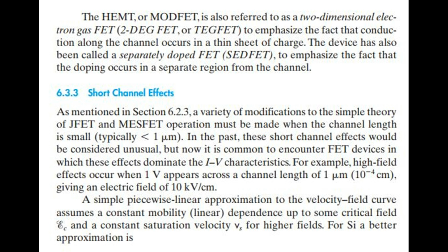The high electron mobility transistor, or MODFET, is also referred to as a two-dimensional electron gas field effect transistor, 2DEGFET, or TEGFET, to emphasize the fact that conduction along the channel occurs in a thin sheet of charge. The device has also been called a separately doped FET, SEDFET, to emphasize the fact that the doping occurs in a separate region from the channel.